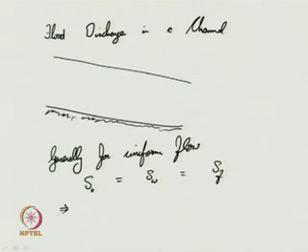To approximate uniform flow in those natural streams or rivers, you have to suggest that your bed slope is approximately equal to your energy slope, or approximately equal to the water surface slope. You need to give certain approximation, then only the uniform flow approximations can be employed for natural flow.